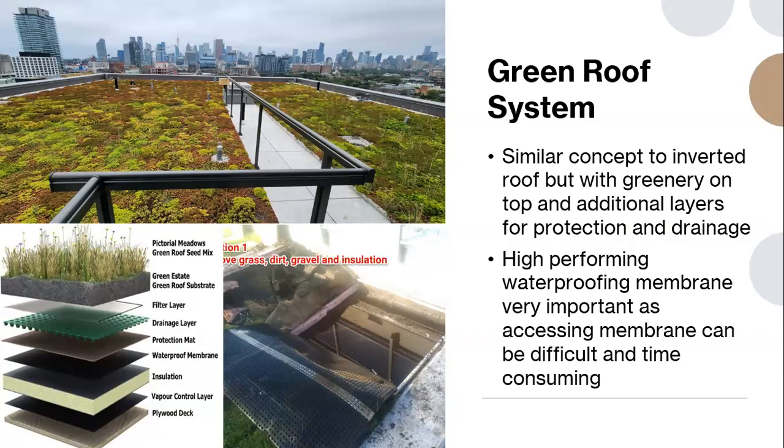Perfect. And Michelle, I've got a couple other questions submitted. Can we change the present roof into a green roof system? Will there be an issue for the load on the roof? It depends on what type of roof system you currently have. I think you would have to consult an engineer. You would have to get a roof load evaluation done by an engineer. It's really going to depend whether you have an inverted roof or another type of roof, what's below it, and how big the green roof is that you're trying to put on.